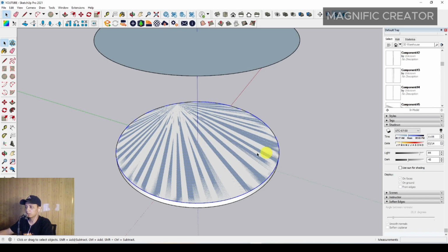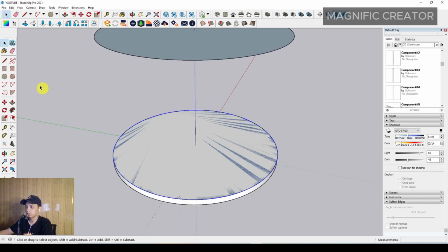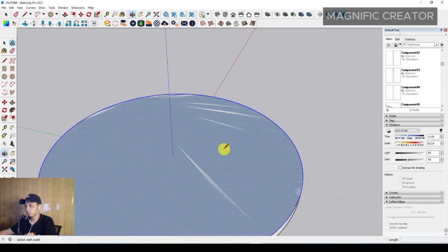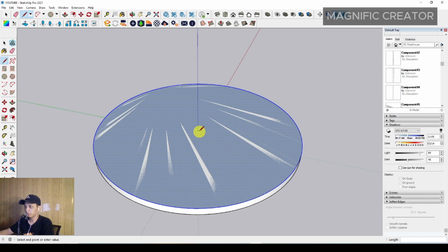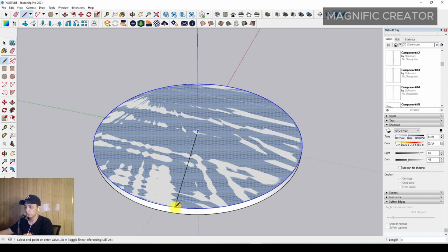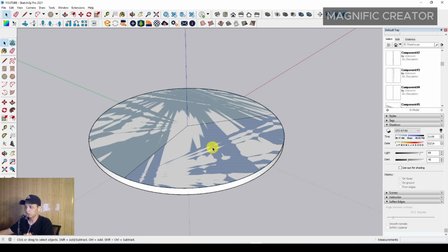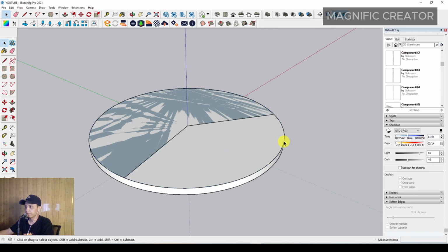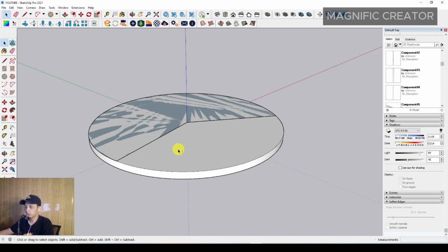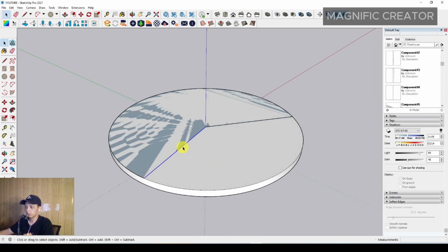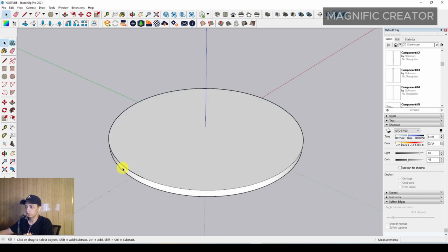Okay, and then we can adjust the opening, adjust the circle opening. Right here we can select the line. We can place it on the middle point of the circle plane. We can set it in here and in here. It's just for example anyway, so you can determine your opening position as your own. Okay, and then you have to right click and erase some unnecessary lines and planes over there. Then you can delete it also, erase it, and it's just one incomplete curve line in here.